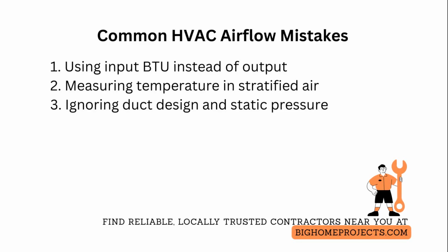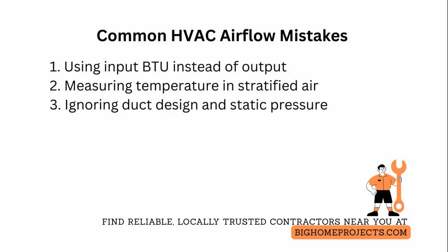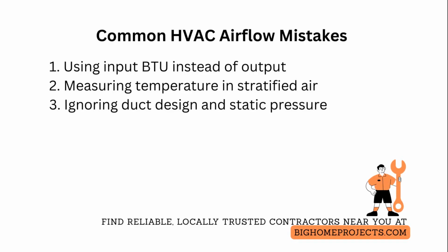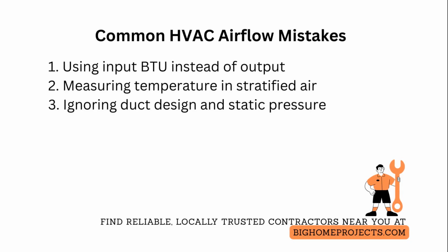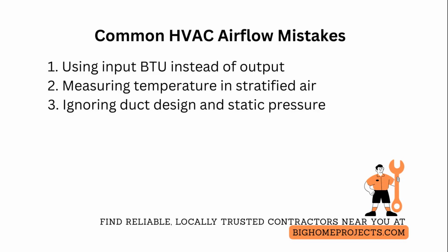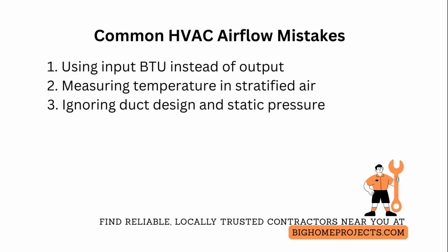A frequent error in airflow diagnostics is ignoring duct design and total external static pressure. Instead of focusing only on blower motor speed, measure supply and return static pressures. Look for high return static that screams undersized or blocked returns, then open additional return grills, reduce restrictive filter media, or upsize duct trunks to bring static and airflow back into spec.